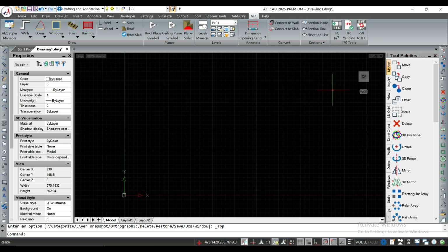Since I brought up the view cube, let's go there next. And then we'll return to the right side of the viewport controls. Normally displayed in its compact manner, it becomes fully visible and functional when you roll over it with your cursor. Outside of the cube itself, there are some icons. One is a house and another is a down arrow. You can set various settings with them, including designating the current view as your home view, which you can return to at any time by clicking on the house.